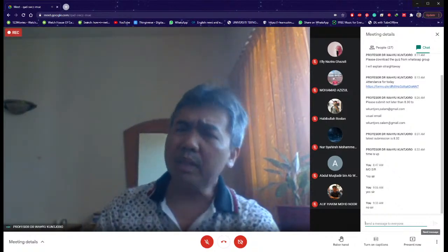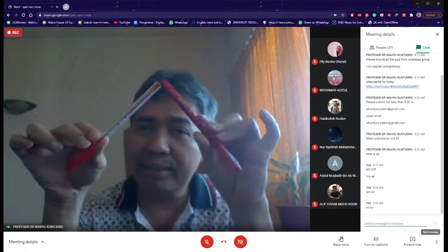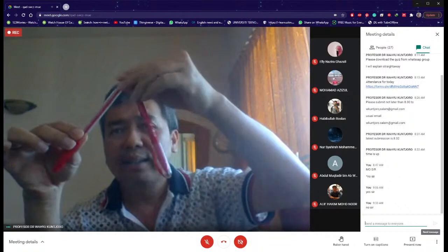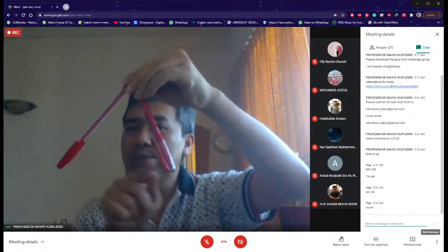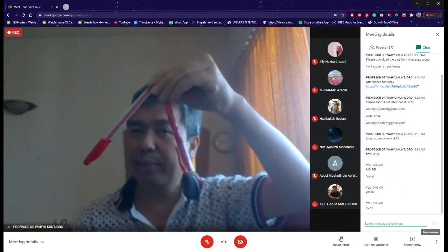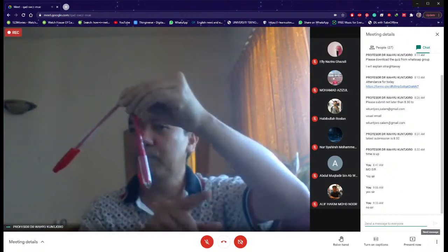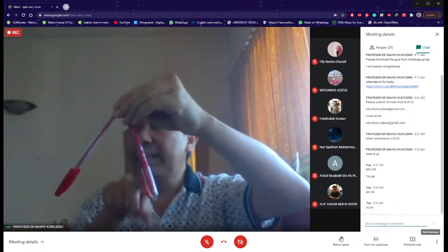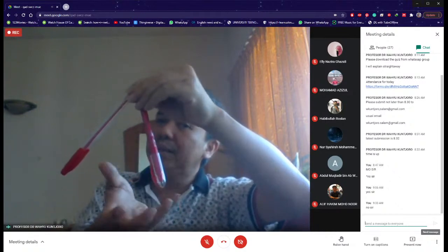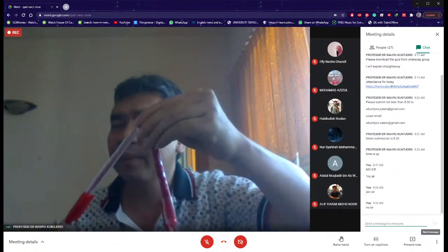Now what about frame? If these two I connect by welding over there, and the support is fixed, meaning that the support is clamped, then of course it cannot do displacement horizontal, it cannot do displacement vertical, and it cannot rotate. If it cannot rotate, that means it will have moment reaction. Then of course we are talking frame.